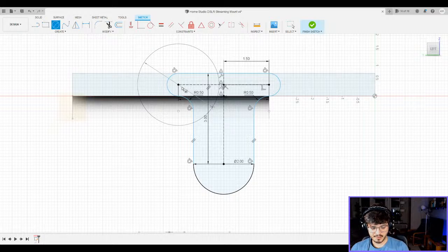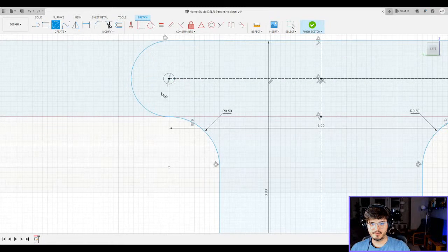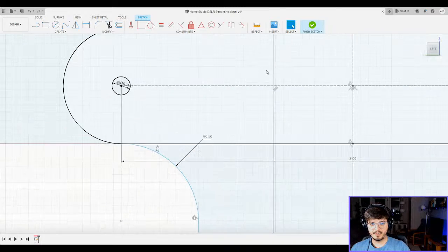Now, obviously this is in inches, but if you add in millimeters, it can convert it right away, which is fantastic. So I'm going to put in, do I want it to bite into the plastic or not? I'm going to do 2.75 millimeters, and the screw is just going to go into that. Now, I have to make sure that I get 2.75 millimeter screws. What if I did 3? Would someone hate me if I did 3? I might hate myself, but whatever.